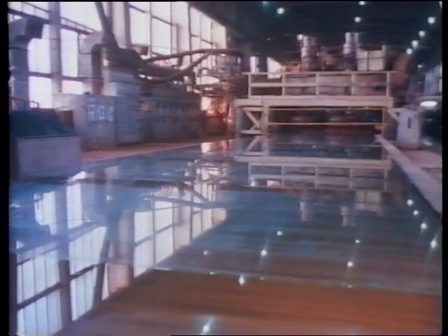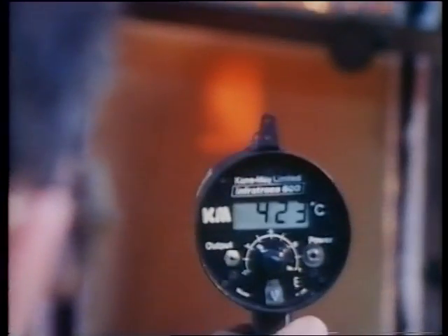Surface grinding of cast wired glass and subsequent polishing turns it into a transparent one. The grinding medium is sand and water. Then, using a mixture of rouge and water, the glass is polished. Both types, translucent and transparent, are remarkably resistant to flames and smoke and keep them at bay for more than an hour. Georgian wired glass has many uses, including fire-resistant partitioning wherever people congregate.